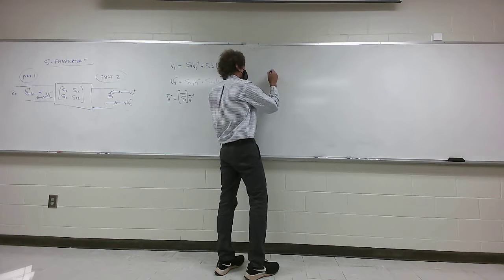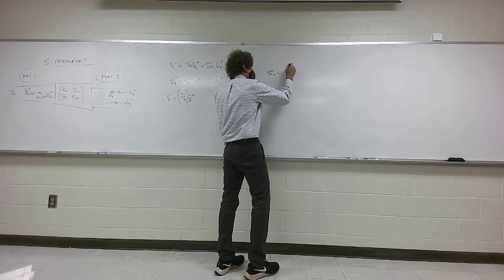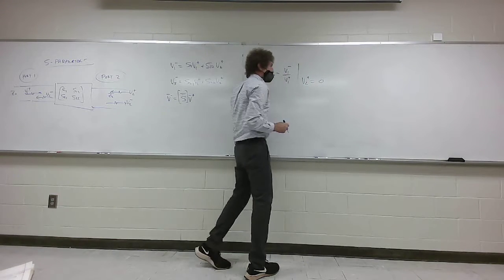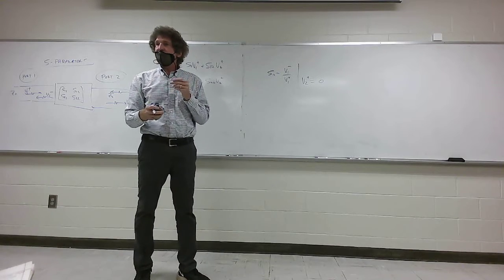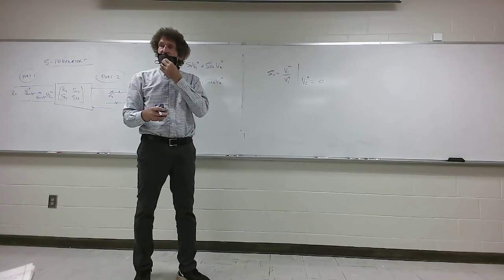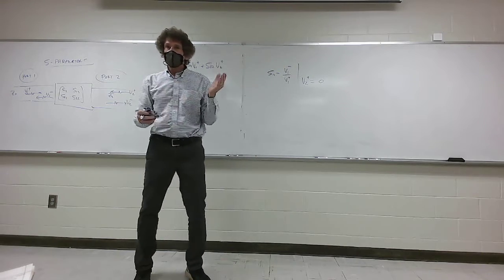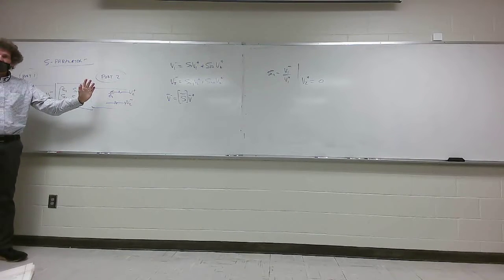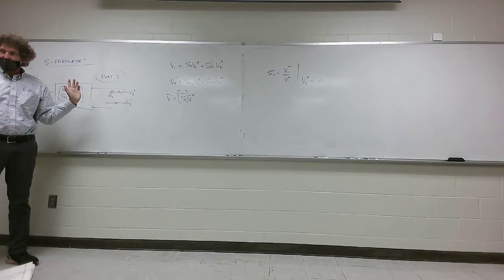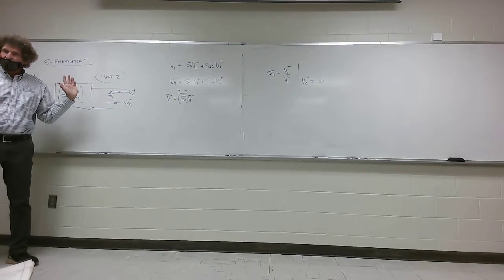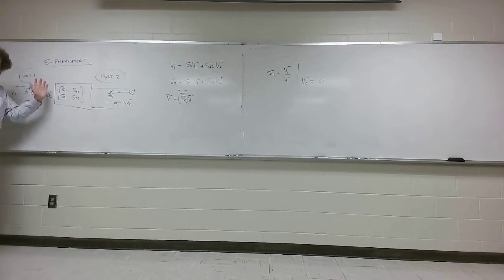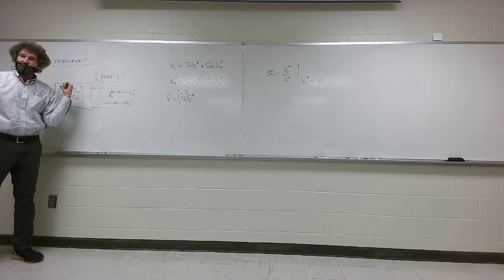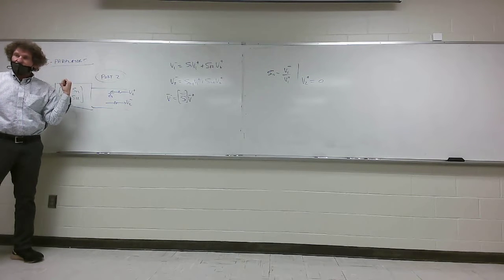When you look at S11, it's really V1 minus over V1 plus, assuming V2 plus equals 0. Now, what that means is this. It's the reflection coefficient. That's all it is. If you have this port, now they call it matched, if this has a characteristic impedance Z naught, and I terminate it onto Z naught, now listen to this point, this is an important point. Then anything that comes in here, some of it's going to get out, but nothing will be reflected back this way, so there is no V2 plus. Y'all follow me on that, class? I'll do an example. How many understand that?